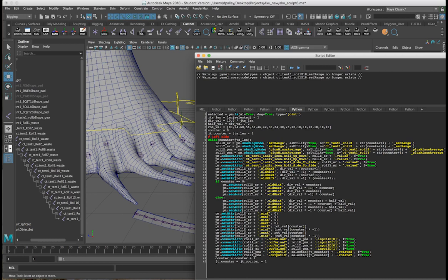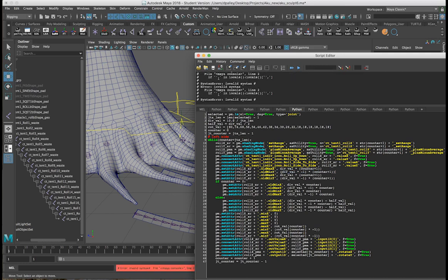And you'll notice I use min here for the y, because when we're dealing with the negatives, the lower value, meaning the higher negative value, is the minimum. So in this case, for the positive, it would be old min 0, old max the increment value. For the decreasing, the old max would be 0 and the old min would be the negative number. I know it can be kind of confusing, but that's how the set ranges are. I'll show you all that once I actually run the script.